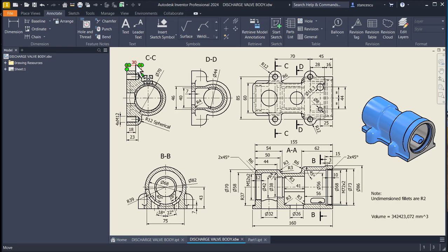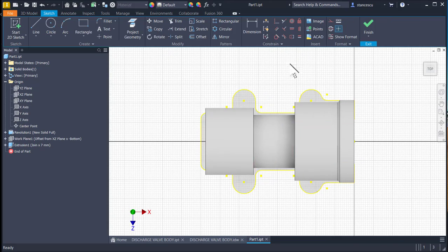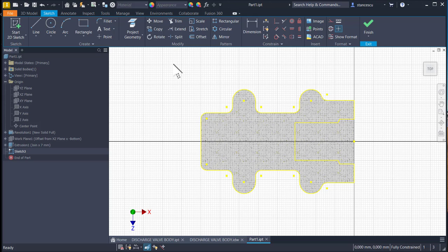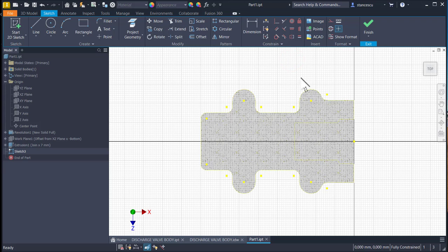Good. Let's see what the dimensions are. 30, and we respect the actual contour here. The value for extrusion is 30. The plane is this one, F7. Everything has construction, but not the arcs.